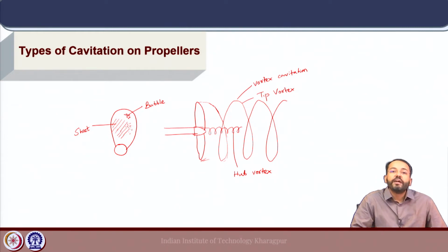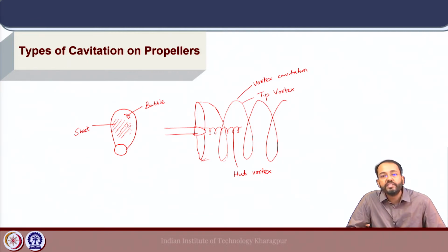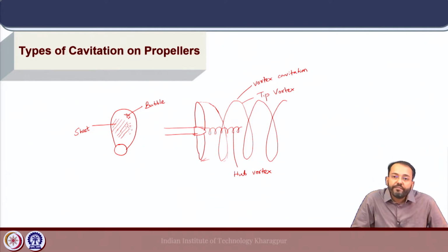Okay. So, cavitation may occur on the blade surface on different parts as we have seen. So, on the leading edge, trailing edge, also near the root or tip, and also in the slipstream of the propeller, which is mainly the vortex cavitations. So, cavitation has many effects on the propeller blade. We have seen that it leads to reduction of the thrust and torque and finally propeller performance, and also more detrimental effects for bubble cavitation include the formation and implosion of bubbles on the propeller blade, which leads to erosion and damage of the blades, and finally it can also lead to vibrations and noise.